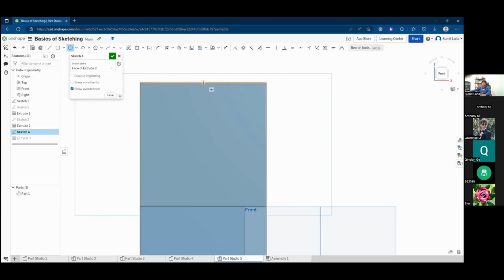If you get on it and then bring your mouse out, it starts to become a dotted line. That line is the center of the top, and you can come over to the side on the right. When you come out far enough, both of those lines will intersect, and when you click on it, that is the center. Can you see how I did that? You want me to do it again?